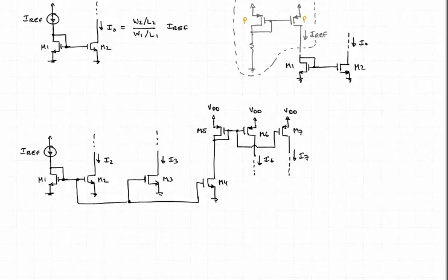So once you have one current source, Iref, you can then mirror that multiple times. And here in this circuit, I'm showing 4 different replications. So we have I2, we have I3. These are both considered, technically we'd say these are current sinks. And then we would have I6 and I7, which are current sources.